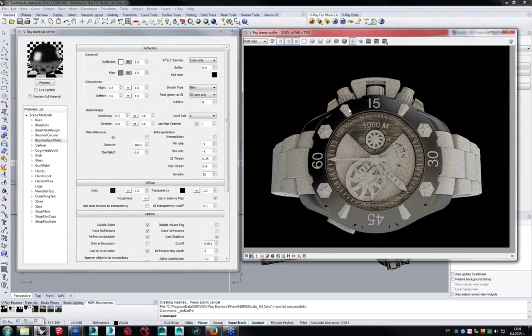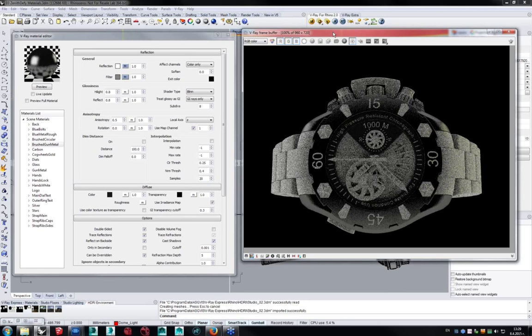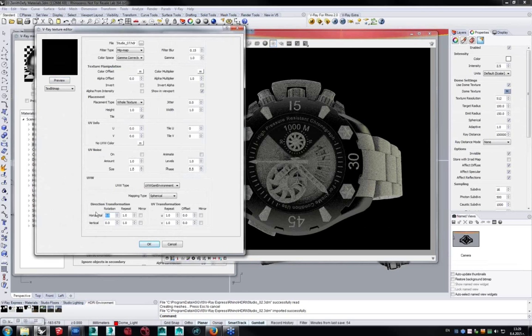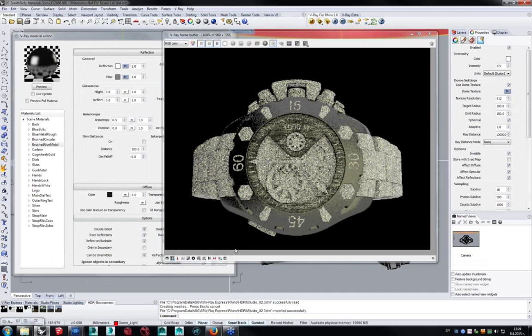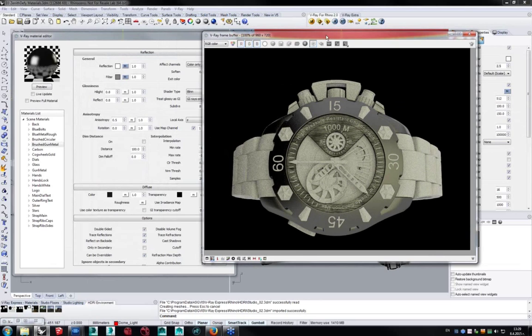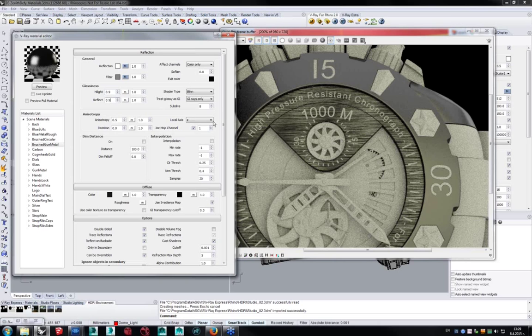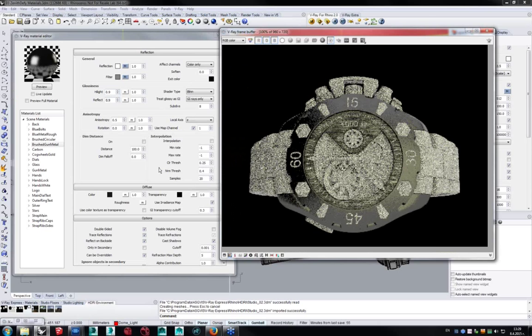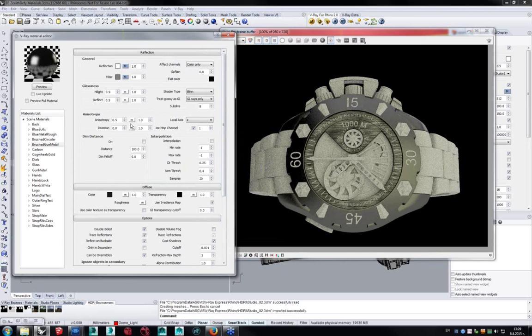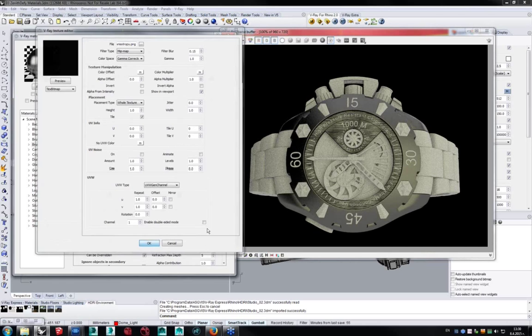So there we go. Again, we're having this yellowish tint to our lighting, which is something I don't want though, so I will change my lighting again to something different. Okay, so obviously this is something where I want to change the rotation. I want you to see that the V-Ray Express toolbar is really easy to work with. Again, it's yellowish. It's a studio setup, but anyway, let's keep it as it is for now, just to determine our reflections. Maybe the glossiness is too low. Let's just add some more glossiness. There we go. And now for the anisotropy, we can select a map here for it, so we can determine the amount of anisotropy based on a map.